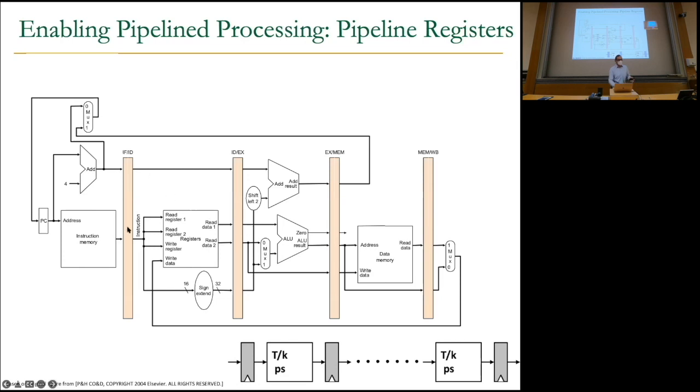And for example, what is in these registers is of course the question, right? In this first cycle, here you're fetching one instruction. At the end of the cycle, you latch something. Right? And then you of course have the program counter, which is a register as well that was already there anyway. So at the end of the cycle, you have the instruction register and PC+4 because you may need it later for branching or something else, for exception handling, as we will see later on. But basically, at the end of the stage, you have the instruction in this pipeline register.